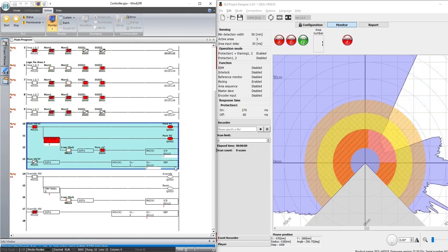I'll bring the object, it's in the protection zone now. But the OSSD signal, the protection zone signal, is showing a healthy state because we have bypassed the specific area. Let's say I'm moving the object to the protection zone now. So a small area has come into the protection zone. What happens now? Even in this case, it should bypass that area.